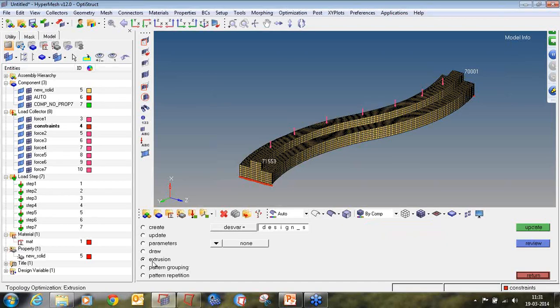On the fifth, you can see the extrusion radio button. Select the design variable. Switch none to no twist. The extrusion constraint can be applied to domains characterized by non-twisted cross-section or twisted cross-section by using no twist or twist parameters respectively. Select the primary path and select node list by clicking on nodes by path.